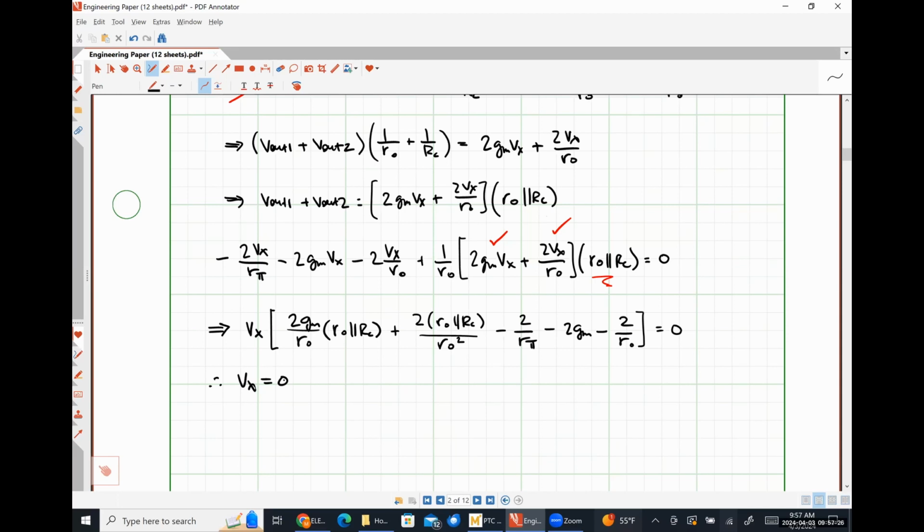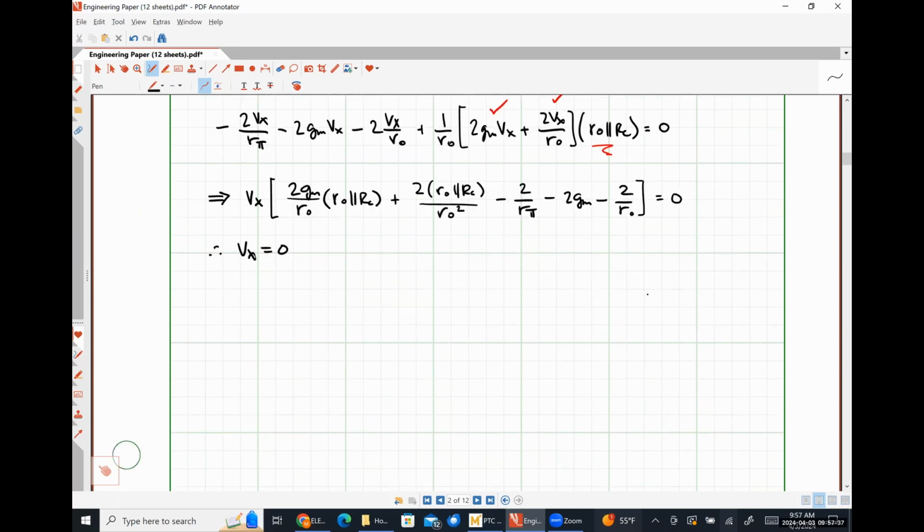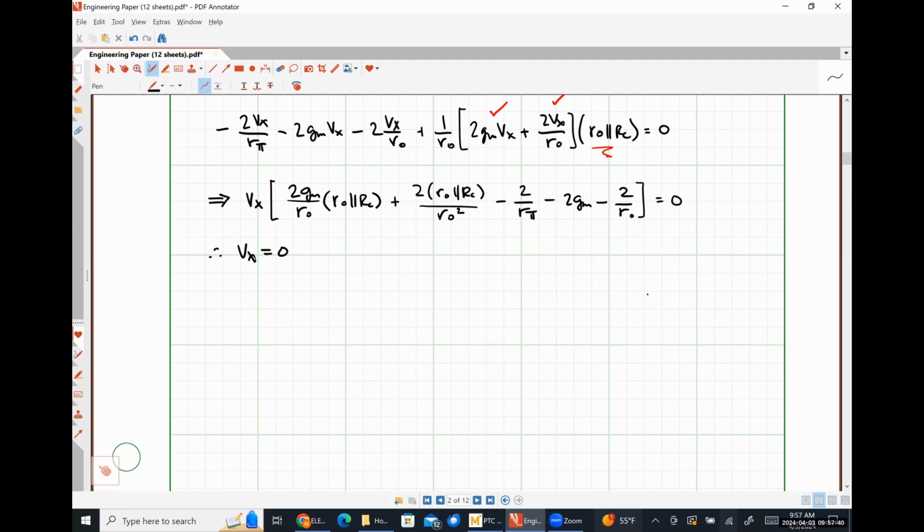So even though that node is floating from a small signal perspective, meaning that it's representing that open circuit from the independent current source on a small signal, because this circuit is perfectly symmetrical, it's going to look like it was connected directly to ground. Anytime we have a symmetrical circuit, which will happen pretty regularly, especially when dealing with things based on differential pair amplifiers, we can just treat that emitter node as if it were connected to ground and go on about our analysis. Even if it's not 100% symmetric, but very close to symmetric, we should know that the voltage at that node should be very close to ground. Okay, and we'll talk about that more in a couple of days.